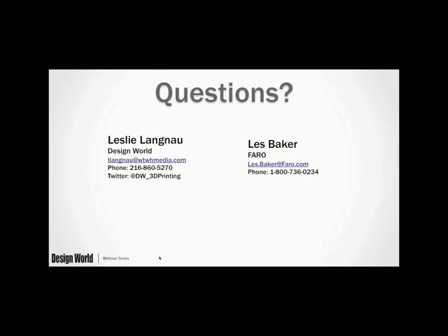Back to the question about whether or not you were going to make a solid part. There's a part 2 to that question, and the question was they were curious about the process of getting the solid part files created. Could you go into that process a little bit? Well, you would use your CAD software. There are so many different options out there. For example, I know that Andrew Sigerson used SolidWorks. So they import that geometry into SolidWorks, and it comes in as planes, as cylinders, as cones, as circles. And you would just model with it in the way that you would model as if you were modeling something from scratch. You would use those circles and planes as the basis for your sketches.